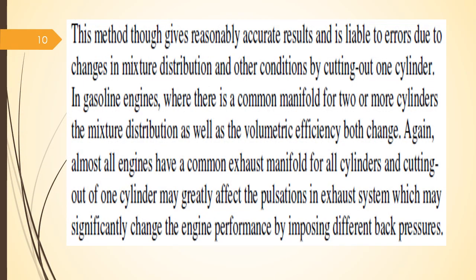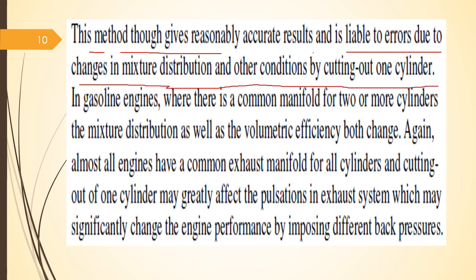So this method is good enough, though it gives reasonably accurate results, and it is liable to error due to the change in the mixture distribution and other conditions by cutting one cylinder. When we cut a cylinder, there is a change in some conditions in the engine, that is the distribution of the mixture as well as other conditions.